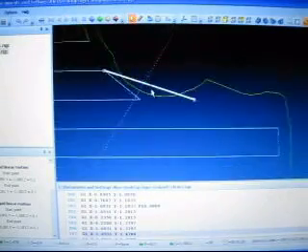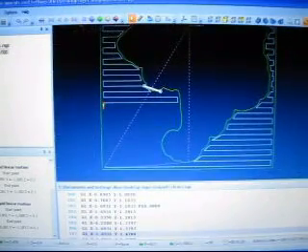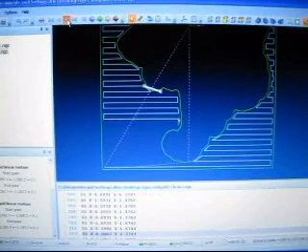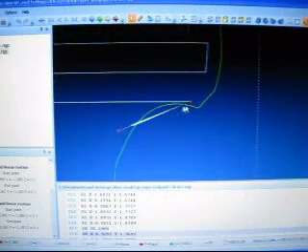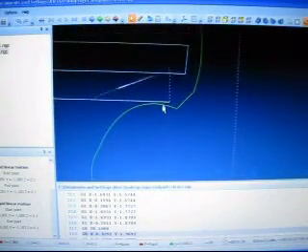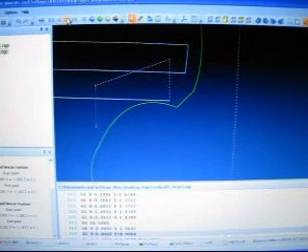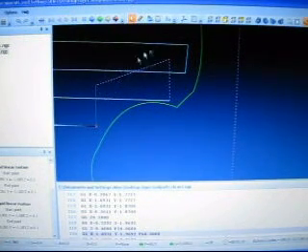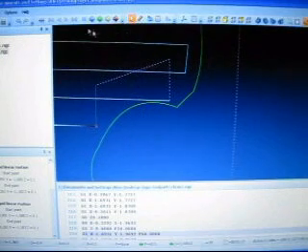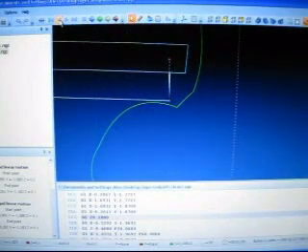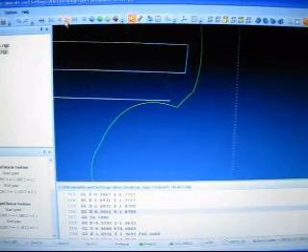So now the toolpath is just going to continue on its merry way until the next point of contention, which is down here by the paw. Now if I zoom in on this, what I want to do here is tilt this up so you can see it. I want to eliminate that little rapid motion because I want to eliminate the plunge. Again, I can't plunge with this bit. It's not a center cutting bit.